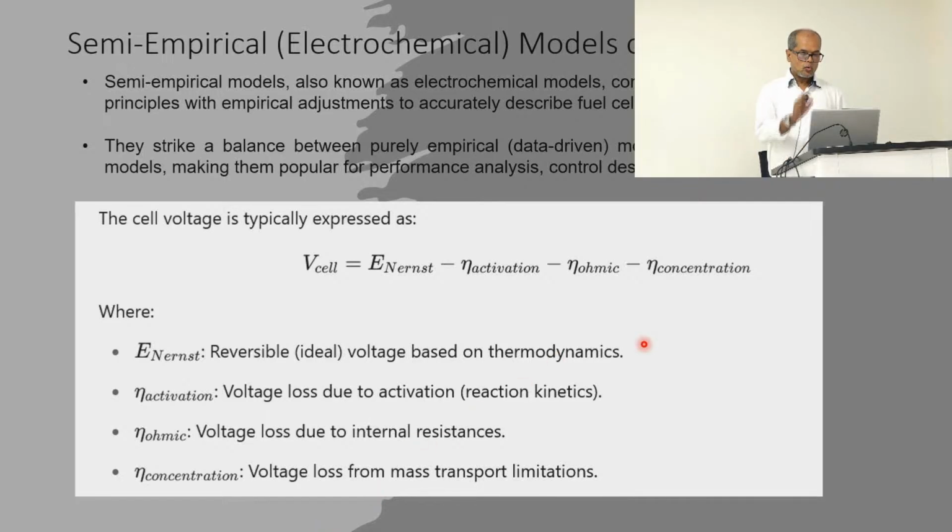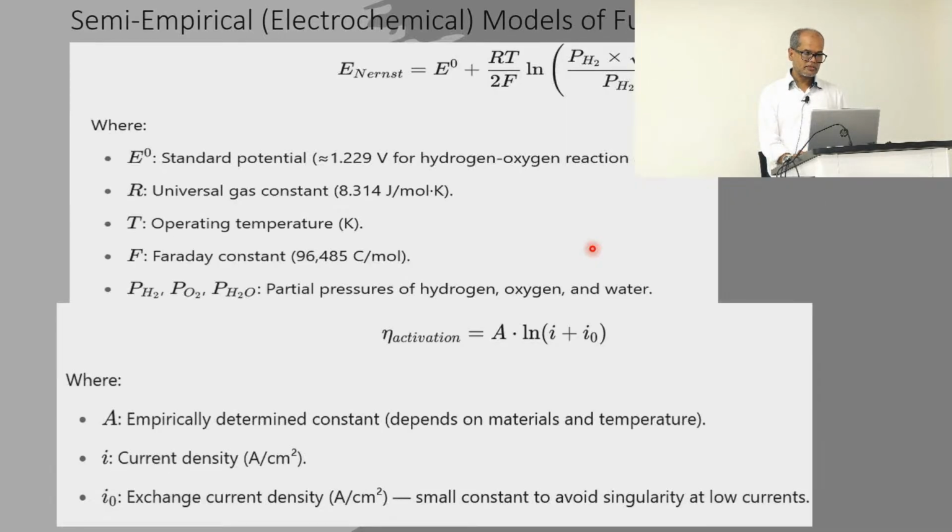So, what we did, we used this model, and then later we used the test results to see whether what we are getting here matches the test measurement, and then we need to make some changes to the model and from the experiment to exactly mimic the behavior of the fuel cell. So, it is just the combination of these two.